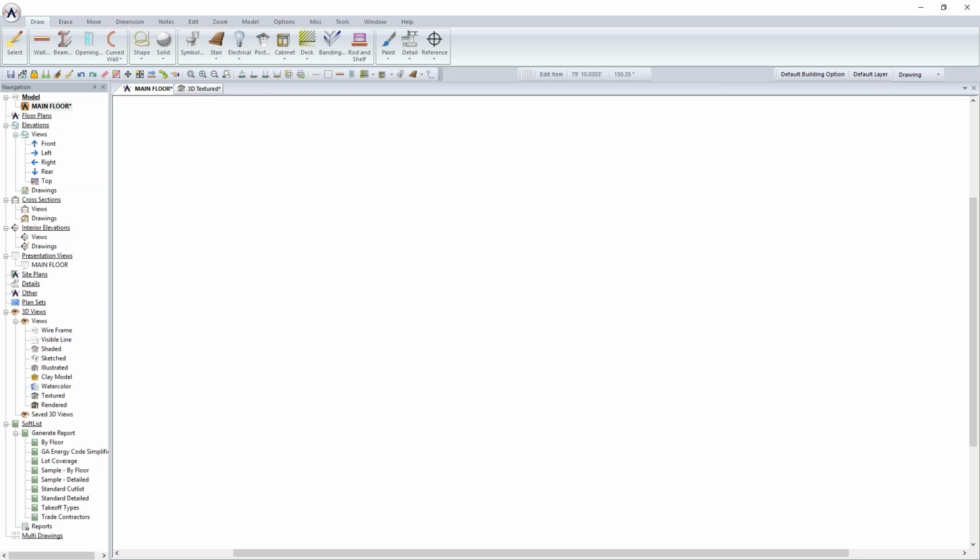All right. Well, you can always do shortcuts. Anytime you choose to do a shortcut, which is to say replace an object by simply drawing or sketching a line, you have shortchanged the BIM model. All right. So my goal is to get you drawing towards that. Use a wall to represent a wall. Use a cabinet to represent cabinets. And when you do that, your model will be that much more complete, and your estimate at the end is going to be that much more accurate.